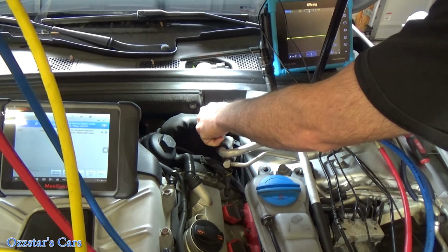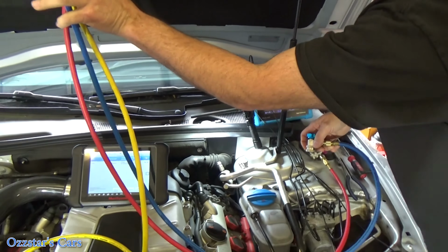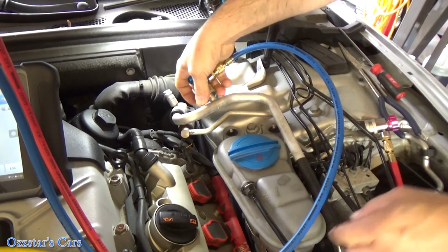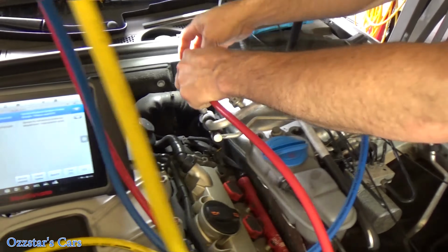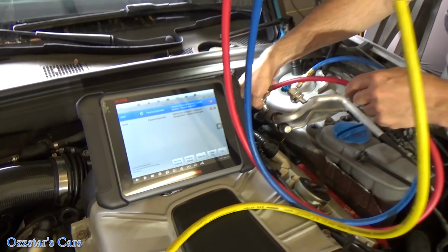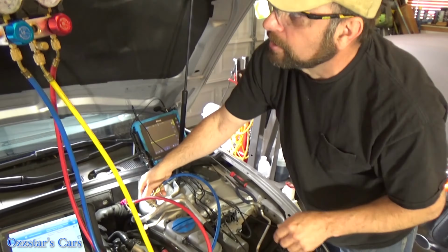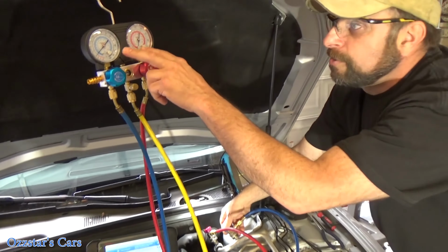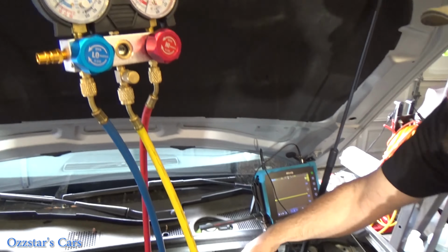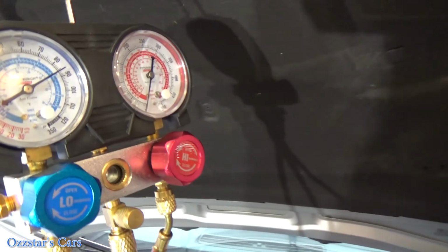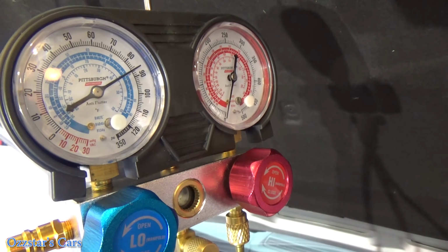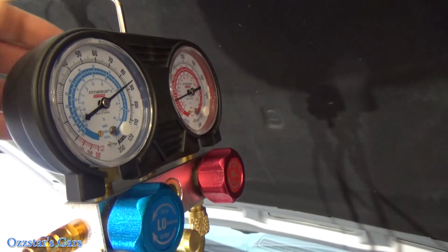And as soon as I connect this, get a shot of these gauges here, we're at 0. This would allow us to verify that we do have pressure. And if you have a bad sensor, basically your scan data is going to show error. It won't show any pressure. So let me open these now, and then you can see these gauges. I'm going to open the low side first, and we should see that go up. That's called static pressure. And now I'm going to go on the high side. Open that one up. There we go.